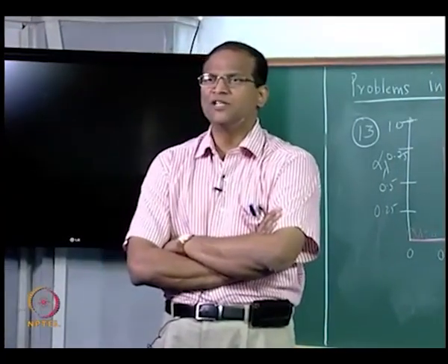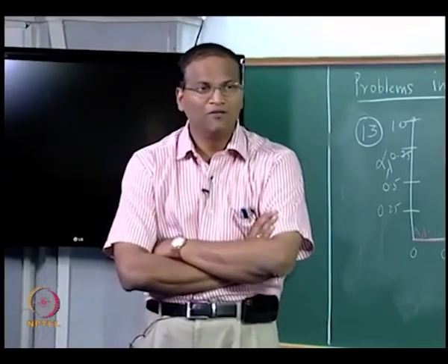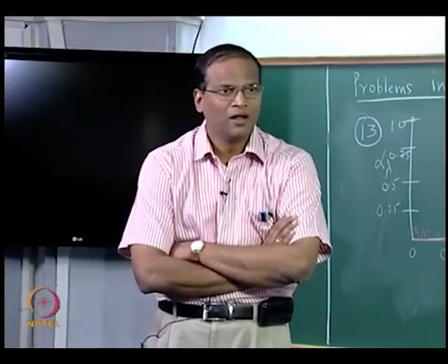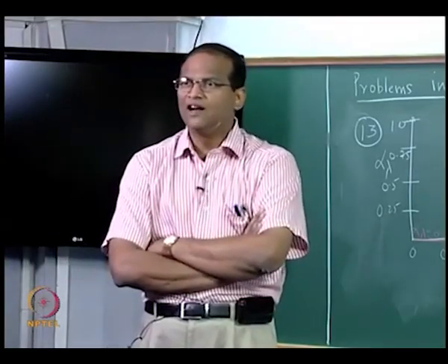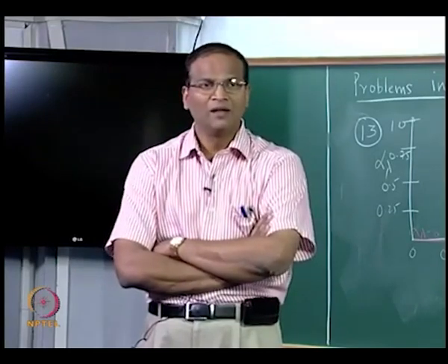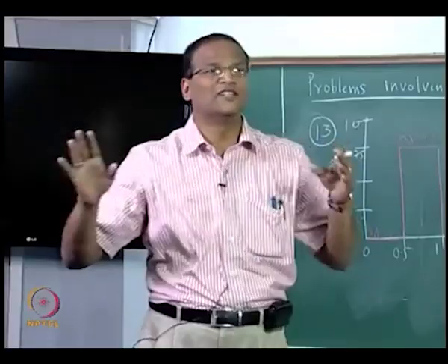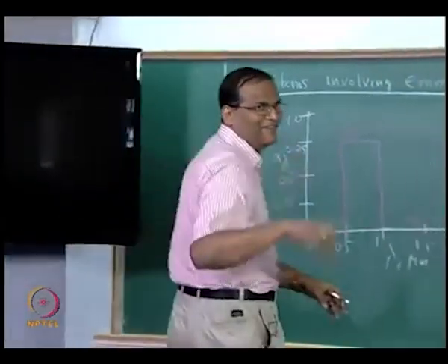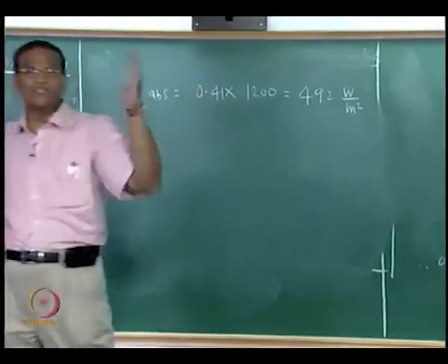Unfortunately, the sun's distribution is not like a rectangular, trapezium or triangle. That follows Planck's law. So we cannot integrate. In the previous problem we just took the area of the trapezium, but here you can't integrate. Because people could not integrate, they figured out the F function chart. That is why that integral between lambda 1 to lambda 2 is given as the F function chart.